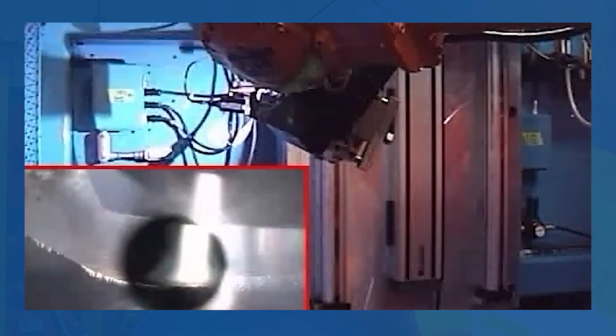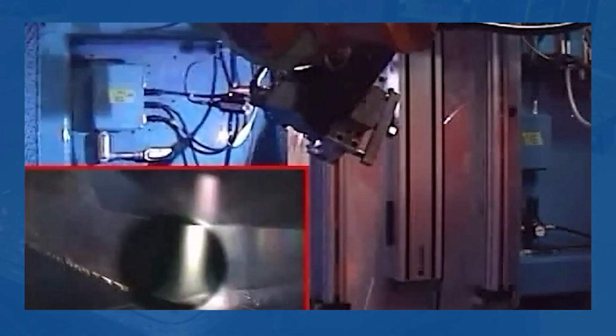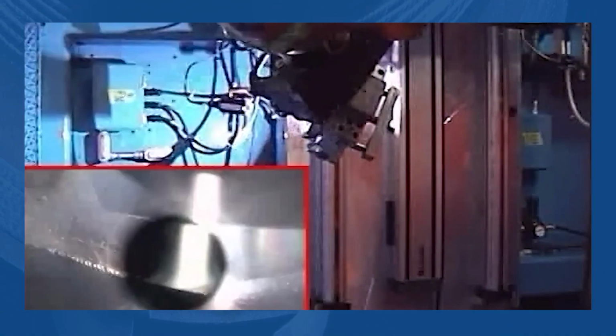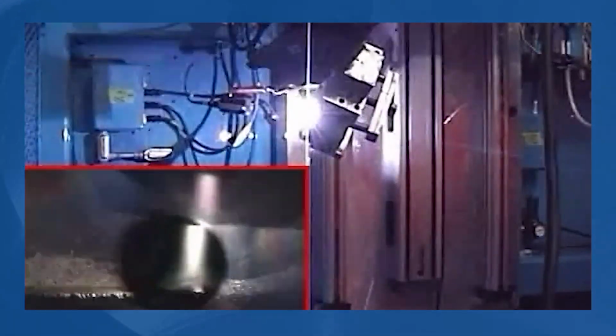In the background, you're seeing some videos of some applications that I think are perfect for plasma. One of them is corrosion resistance. We're using hot wire and plasma to coat the inside of oil field equipment. Plasma does a great job, and the tungsten is shrouded, so we don't have any issues with tungsten contamination. Another one is metal-to-metal wear on a rock bit bearing. It's hard to beat plasma for cobalt overlay. The next one is ground engaging wear, where we're running a composite material with tungsten carbide and a chrome nickel silicon boron matrix, where the part actually rubs against the rock. All these are applications that I consider to be best suited to plasma.